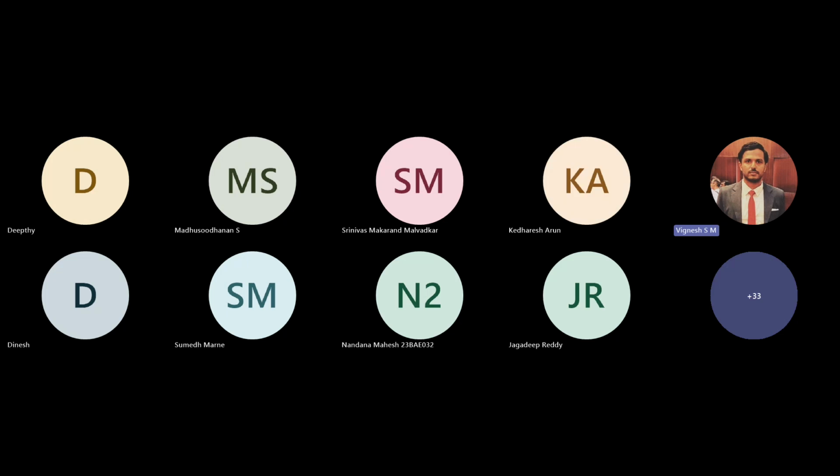Second thing is please use Fluent Meshing, because in Fluent Meshing you can use polyhexcore. This will drastically reduce the computational time and the computational machine which is required. Okay. And the next smart way of doing this is you can use GPU. So please use GPU and make sure you have the right GPU with you. I mean, you must have an idea.